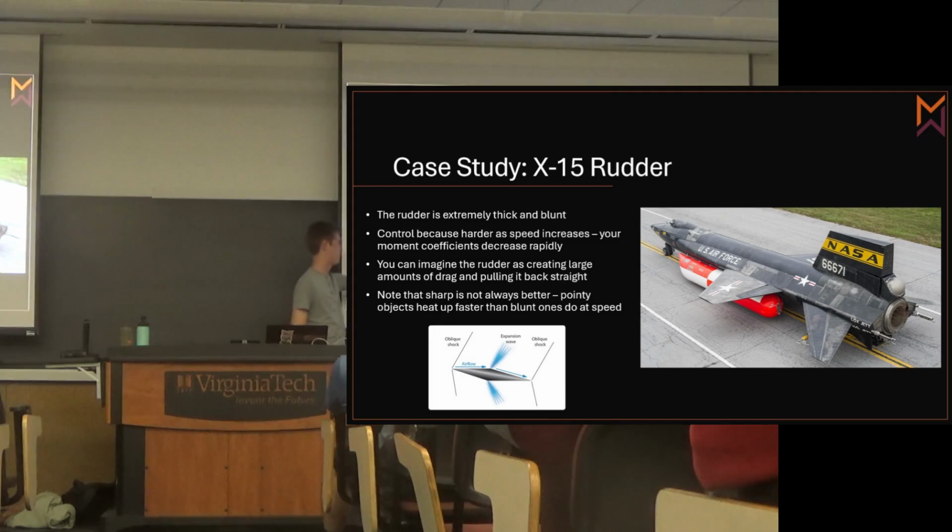This is a typical supersonic airfoil. But you don't want these nice sharp edges because the way the shocks form, it ends up making things a lot hotter. So it's very typical, especially for re-entry, that you have blunted bodies. Blunted bodies are better for heating than the sharp ones, but not as good for going fast.